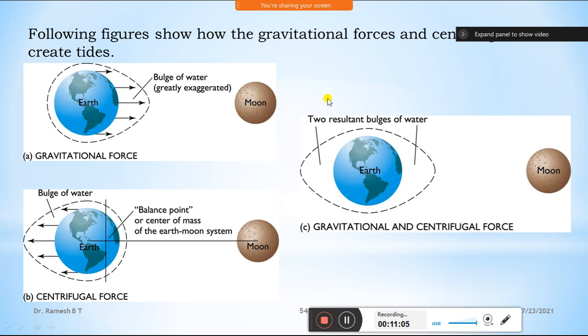The typical mean range is roughly one third of the spring range, and the actual variation is larger or somewhat complicated by a seasonal variation. That is, of course, it depends on the seasonal variations. The variations are periodic, monthly and seasonal, and the range must be taken into account in the design and operation of a tidal power plant. These are all considerations we have to take at the time of designing the tidal power plant.